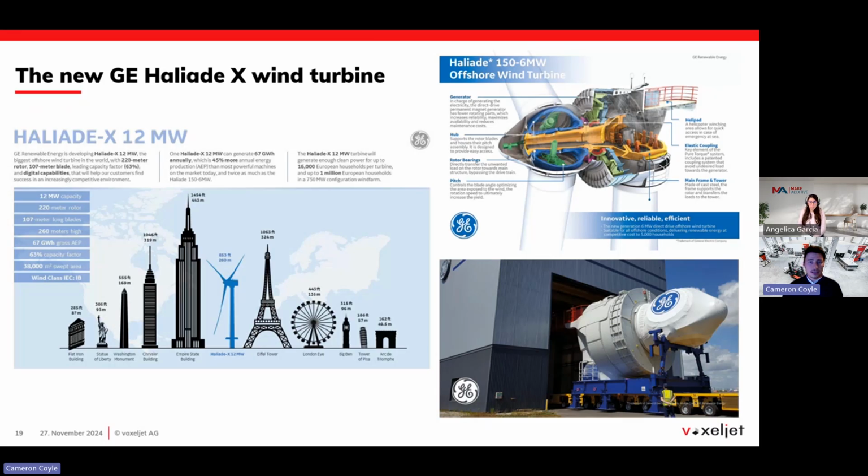And to give you an idea of how much printing that is, it was 72 different pieces, and it took 6 weeks to print on one of these machines. If you can imagine 4 by 2 meters as a build volume, this takes on the printer just over 2 days. So we made 6 weeks of printing in order to make up all of these 72 individual pieces. The parts were made, sent to GE and cast, and the outcome of the test was very positive. And it produced a casting which was more accurate than a casting made through traditional methods.